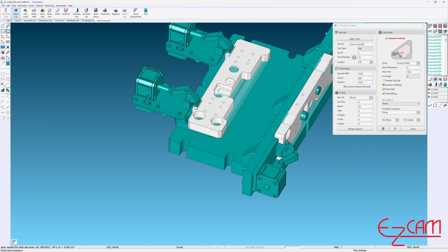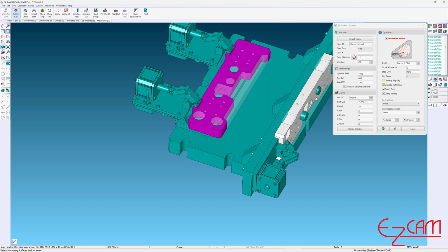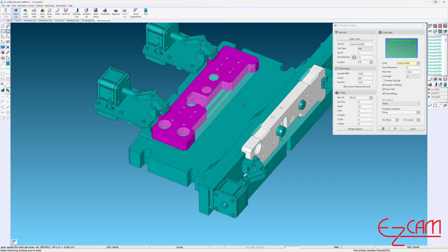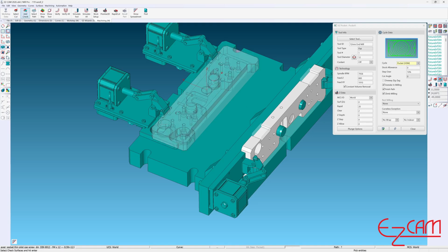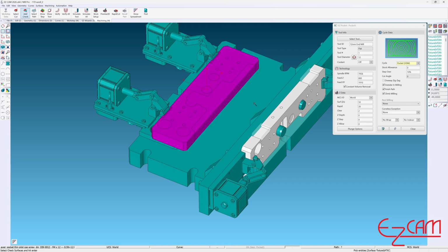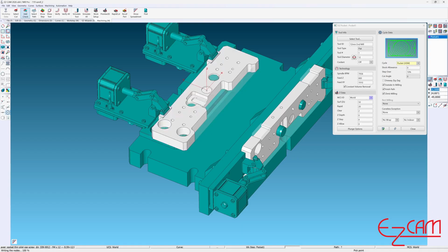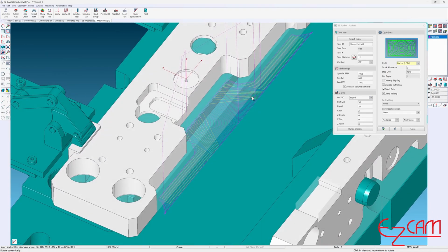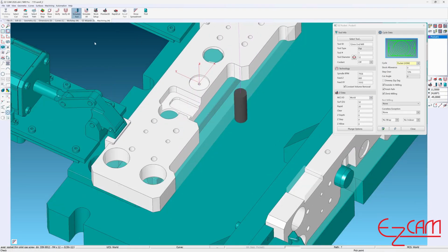Machining surfaces in this step allow the user to partially select the regions to be machined on the part by using Smart Click. In my current example, the entire model needs to be selected, so I hold down the left mouse button and frame the whole model. Then on the right side, I can define to the program that I want the area between the stock and the part to be machined. For this, after clicking the Control Surface command and selecting the stock, we can check the result with Calculate Toolpath.